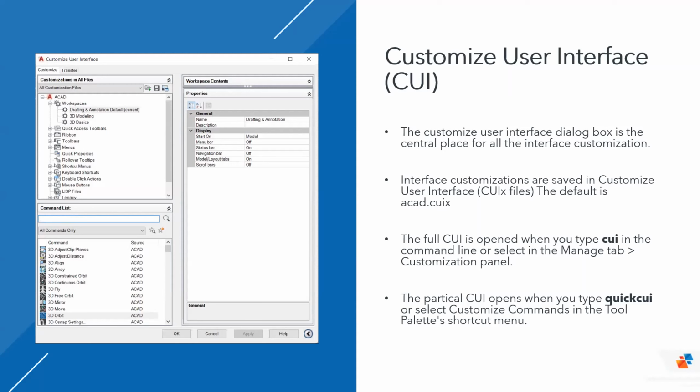So that's easy to manage when you have a number of partial CUI files along with the main one. It's also critical. You don't want to mess up the original one, the out-of-the-box .cui file. So you could have all your custom items saved as partial CUI files too.